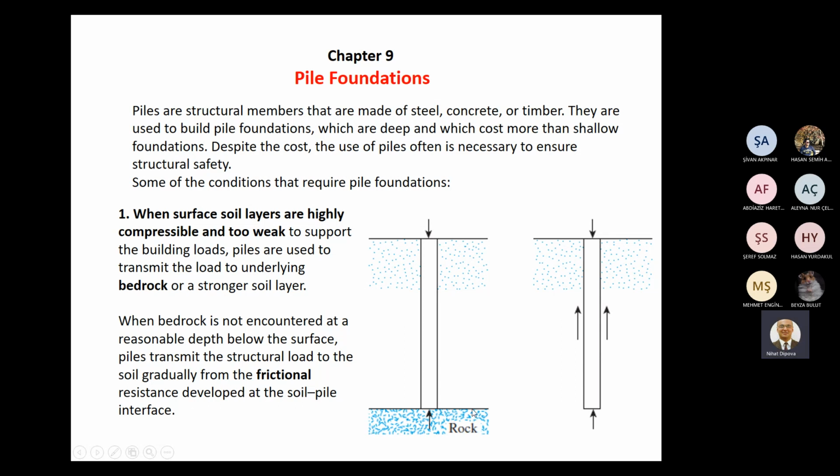But when this strong layer, this may be a rock layer or a firm, hard soil, is not observed at a reasonable depth, in this case we can construct our pile foundation as frictional piles. In Turkish, sürtünme kazığı, frictional piles.